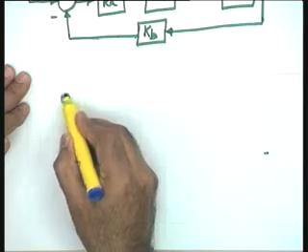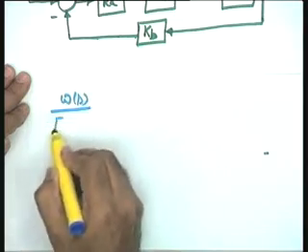Now, if I take up this block diagram and I am interested in the transfer function model of this system, you see that it is a 2 input 1 output system. Let me apply superposition and set one of the inputs equal to 0. Let me set disturbance equal to 0. So, I have a transfer function between omega and Ea, or between theta m and Ea. So, between omega and Ea, please help me, I am sure you are equipped with this now.